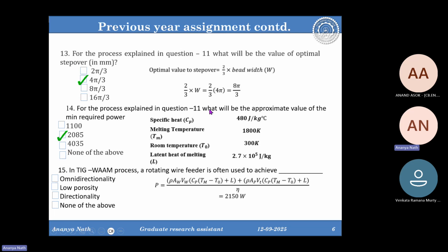So if you are going from here to here, there will be one pattern in the metallographic properties. And when you are going from here to here, your complete melting process changes. Because if the wire is coming from the right direction, you're going from left to right, and now with the same configuration, you're going from right to left. The heat interaction is different, right?